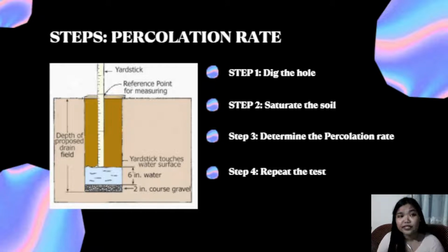Armed with this information, assuming your tests have been a success, you can now go on to determine the most suitable size of drainage field for your foul water system. Advance to my advice on sizing a septic drainage field.